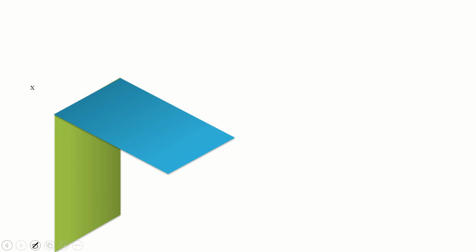Now a point D is in the fourth quadrant. We have HP and VP. We have a point which is 20 mm below and 40 mm in front. This is the position of point D. Now we get the top view like this and the front view is given here.